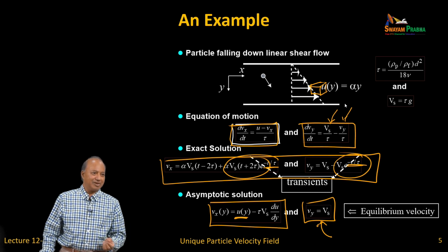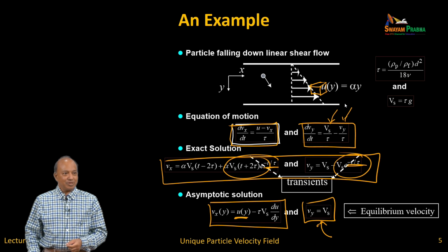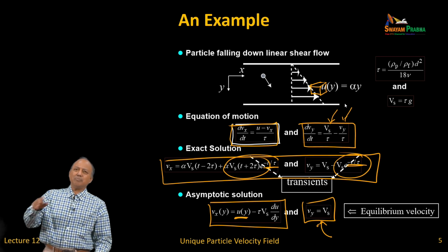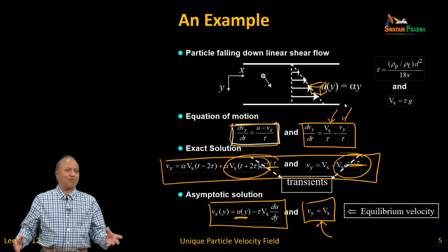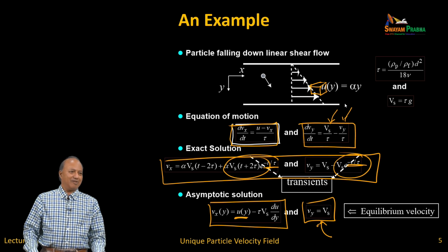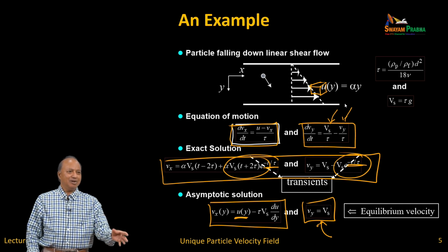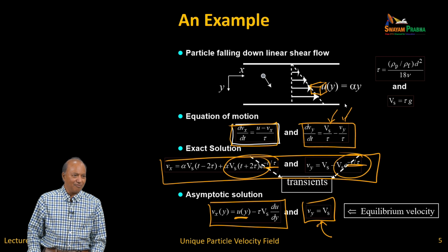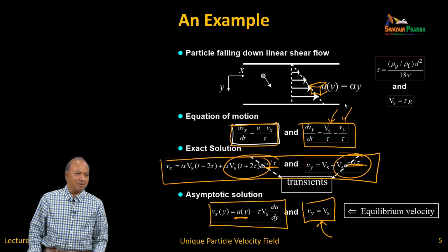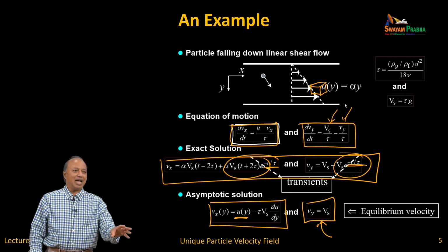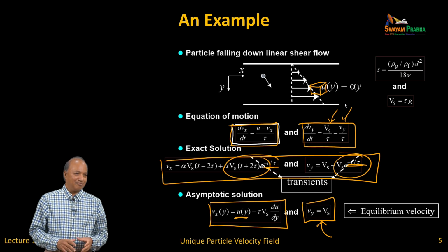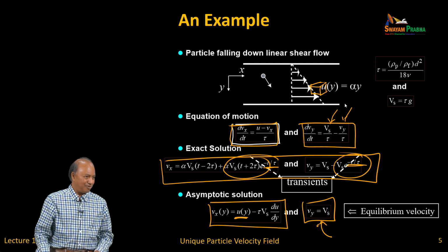So why solve it? What I'm going to talk about is, when Stokes number is 10 to the minus 5, 4, something like that, don't solve anything. Just simply set your particle velocity to be the same as the fluid, particle temperature to be the same as the fluid. You just have to track volume fraction, where they accumulate and so on and so forth. Okay.